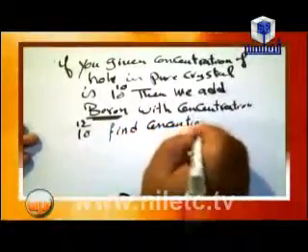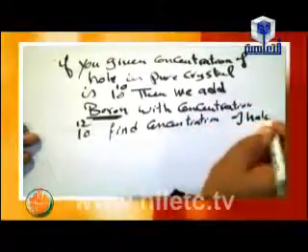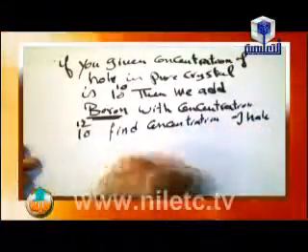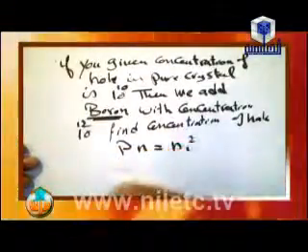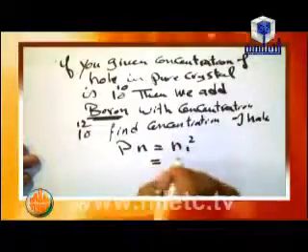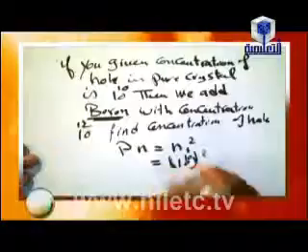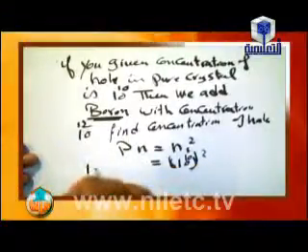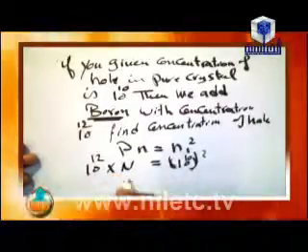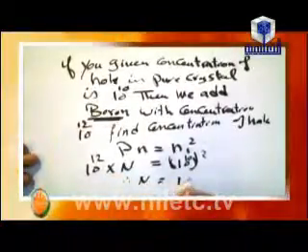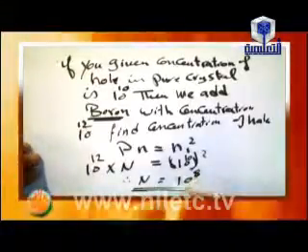Of electrons. We know the law of mass action, pn equals ni square. Ni square is equal to 10 power 10 all squared. So p equals 10 power 12, times n, then n equals 10 power 8. This is the value of concentration.